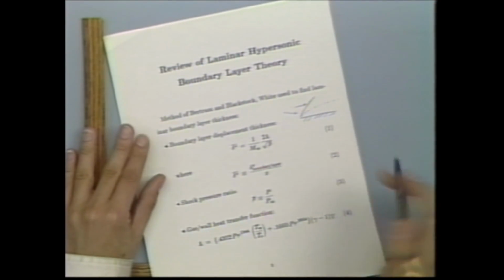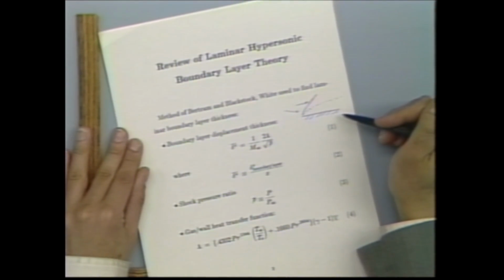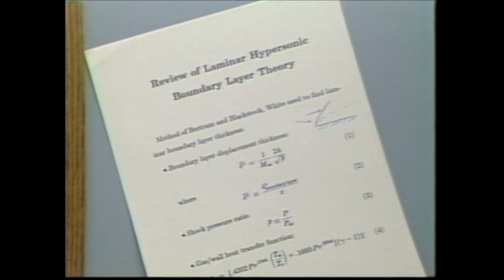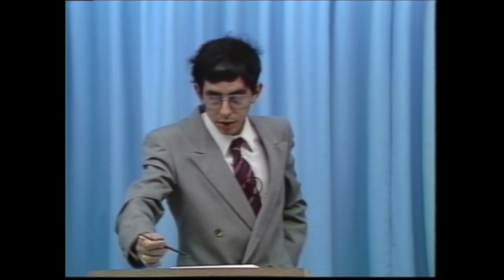As we crank up the surface inclination, we can squeeze down the boundary layer. In fact, the boundary layer height can be very sensitive to the surface inclination, and therefore very sensitive to the angle of attack of the vehicle. So one of the first things we worry about in the boundary layer problem is the sensitivity of the boundary layer to the flight conditions.